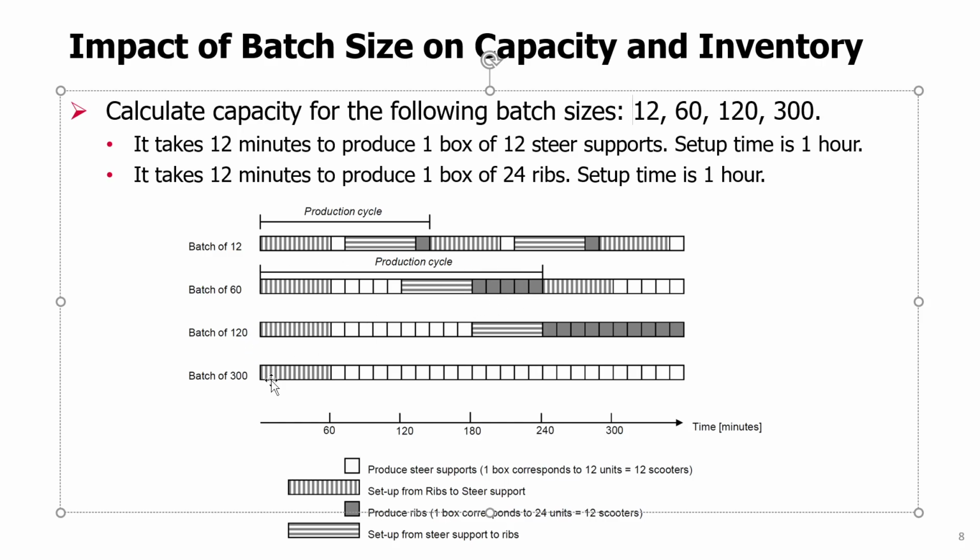And as you increase batch sizes, I hope you see that the setup time becomes a smaller and smaller fraction of the production time. So of course, I hope you see that there is an advantage in introducing larger batches because they make relatively better use of the resource time.